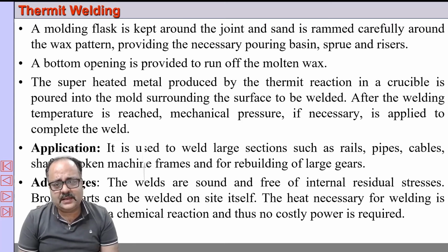The applications, as I have said, are welding or repair of rails, pipes, cables, shafts which are broken, rebuilding of large gears, etc. The advantage is that it gives a sound weld free of internal residues, and broken parts can be welded on site. That's very important in railway tracks.